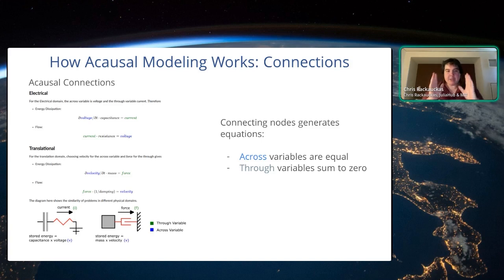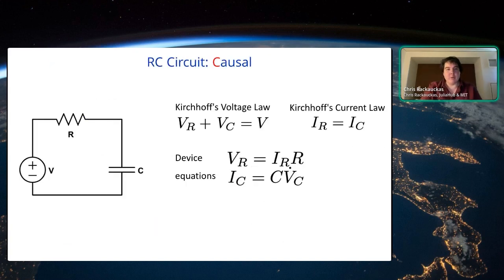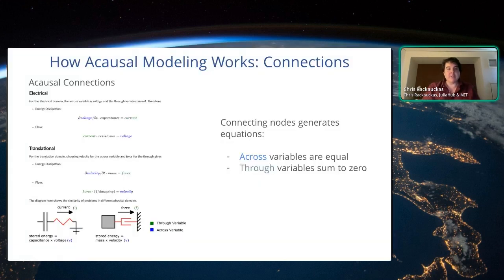And so, why is this important? Well, it's important for multiple reasons. One thing is that it's a restatement of Kirchhoff's voltage and current laws in terms of conservation. Kirchhoff's current law is just conservation of electrons, that they don't disappear as they're moving. And Kirchhoff's voltage law is conservation of energy. Locally, conservation of energy and conservation of current just means that voltages become equal and currents always sum to zero. But this is always true for a lot of other systems as well.